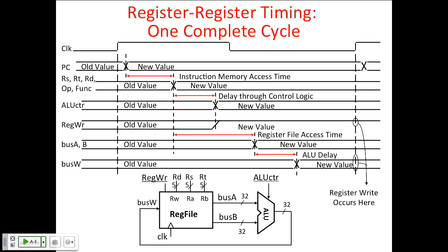Yep, question? Daniel? No, this delay here is just the program counter value, that 32-bit register, from the clock edge to the output of those 32 bits changing. We haven't got to the instruction memory yet.